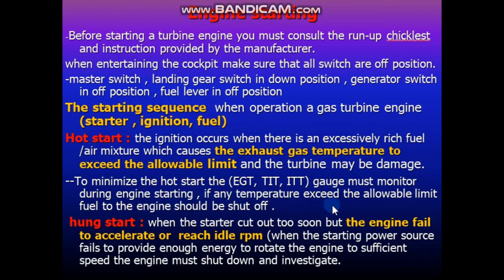If any temperature exceeds the allowable limit, fuel to the engine should be shut off. So if we see the EGT gauge rising, we will cut off the fuel going to the engine. Now hang start.